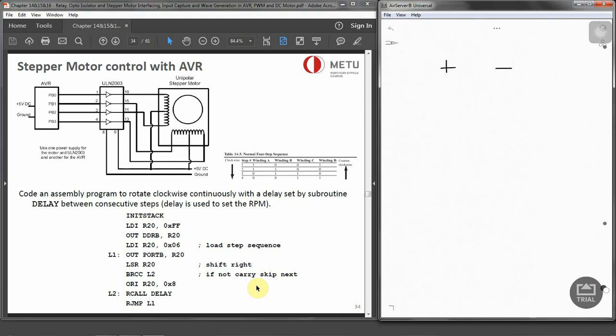Now, with the stepper motors, we have seen that they move in steps of 1 to 15 degrees, but the DC motor moves continuously. With the stepper motor, if we know the starting position, we can count the number of steps the motor has moved and calculate the final position.